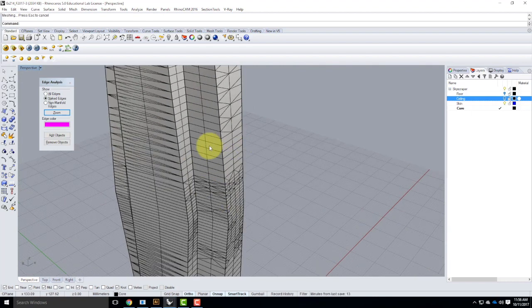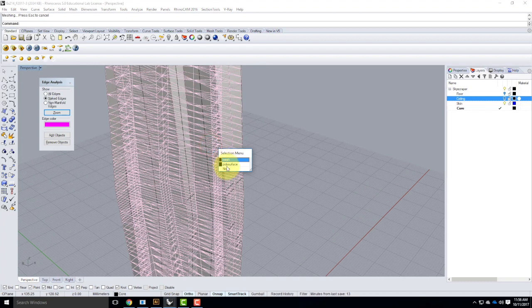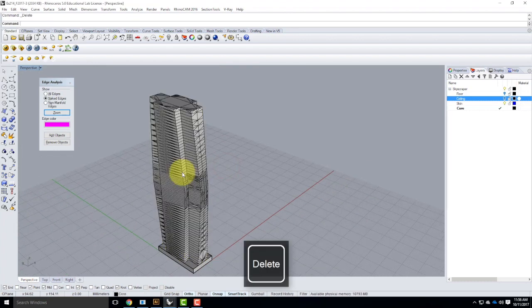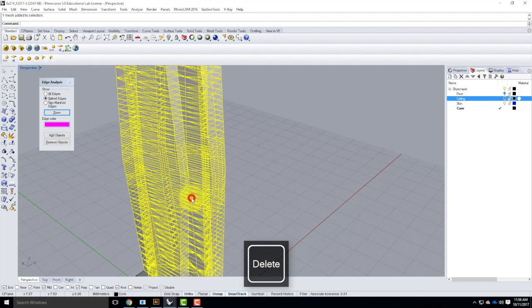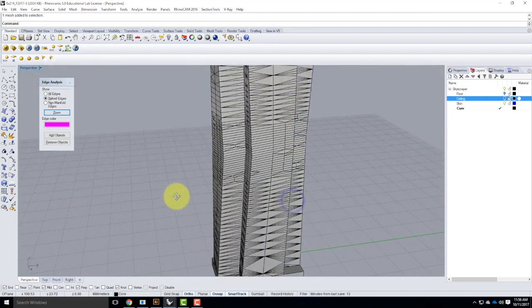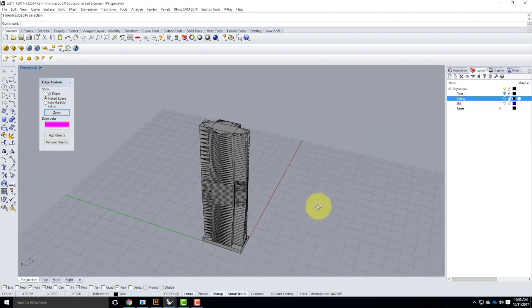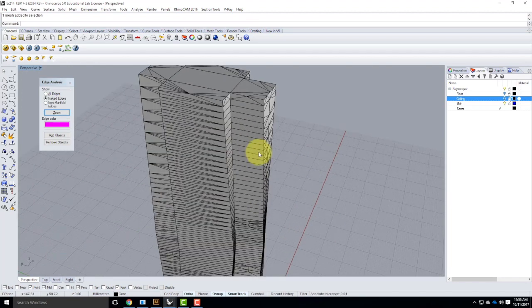It did not delete my original file, my original poly surface. So I actually have to go in and delete that original. Likewise, I'll have to come down here and delete that original so that I'm back to the mesh file. So this is the mesh file that represents my object at this point. I like to do the conversion this way so that I can see what the count is going to be and do I like the accuracy of what's going to ultimately print.